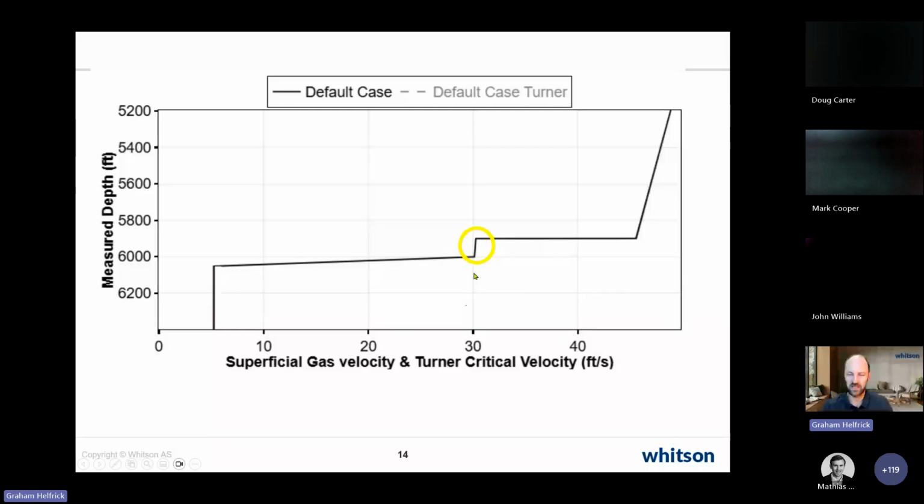As the gas goes through the choke, it's at a lower pressure on the choke outlet, and once it's at a lower pressure, the gas is expanded, and its velocity speeds up again. And then as it goes up the tubing, it keeps speeding up because it's under less pressure. So we can basically plot this velocity everywhere in the wellbore, including on both sides of the choke.